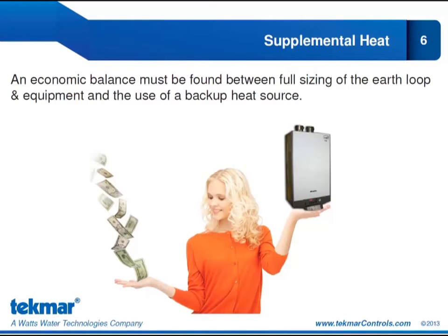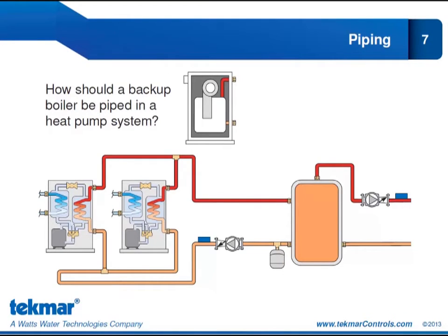Now, we also need that backup heat source if the supply temperatures that our loads need exceed the capacity of our heat pump operating limits. And that's what we're going to look at in this presentation: what kind of design loads may mean that we actually need to have a supplemental heat source, because otherwise we're going to see our heat pump trip out on high pressure limits. Once we've decided to add a backup heat source, in this case a backup boiler, into our system, then we have to ask ourselves how do we properly pipe it into the mechanical layout.